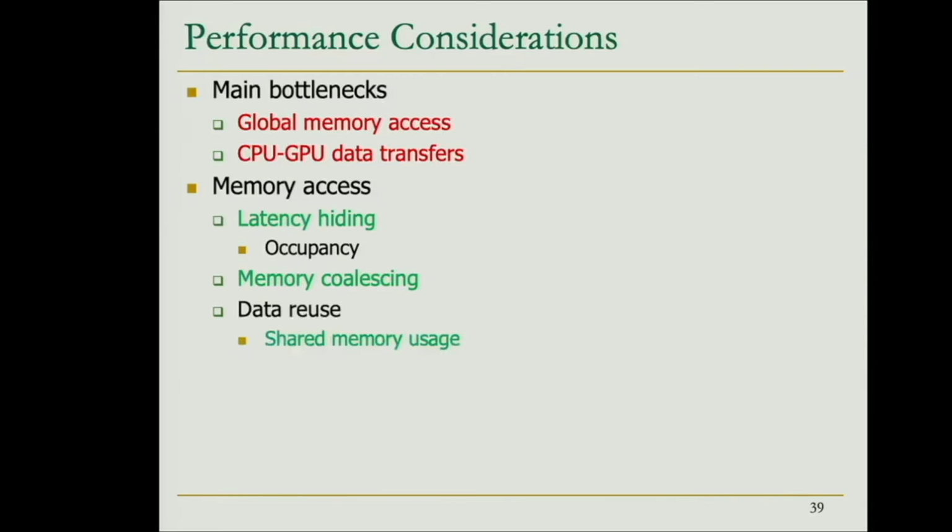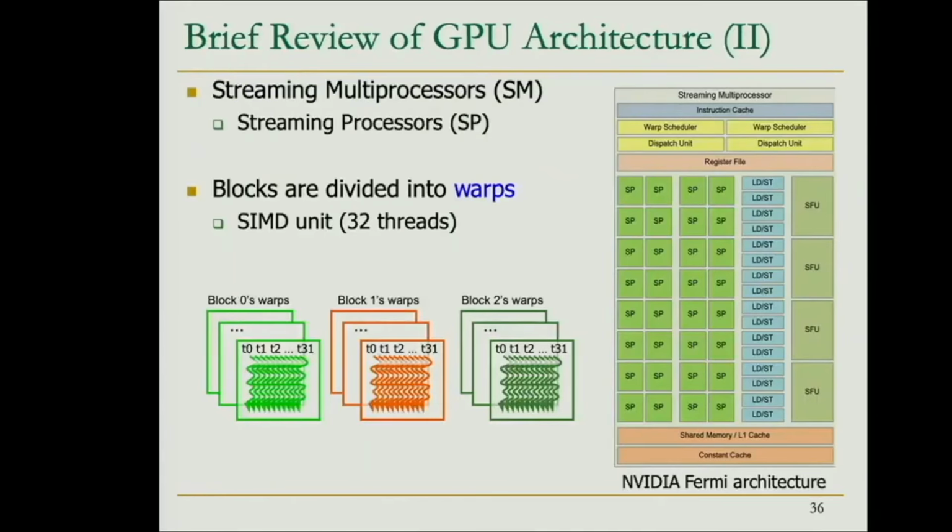Let me go very quickly back. So it's right here. It's this shared memory that, maybe not in all GPUs, but typically, is the same memory space as the L1 cache, and is internal to the streaming processor or GPU core. That's why all these units that we have here can access this shared memory. It's a scratchpad on-chip memory.